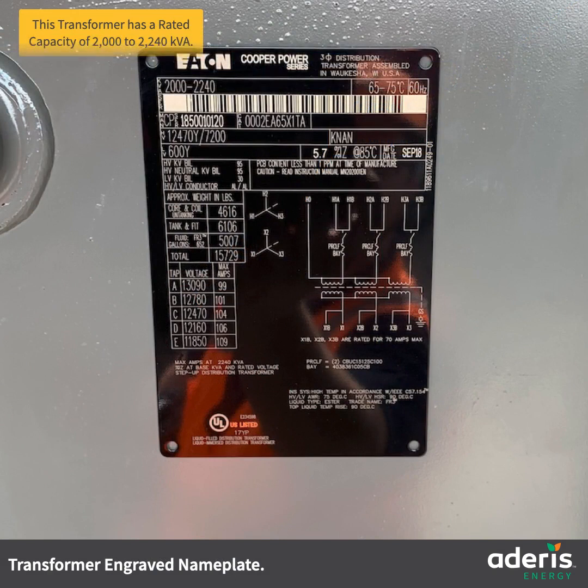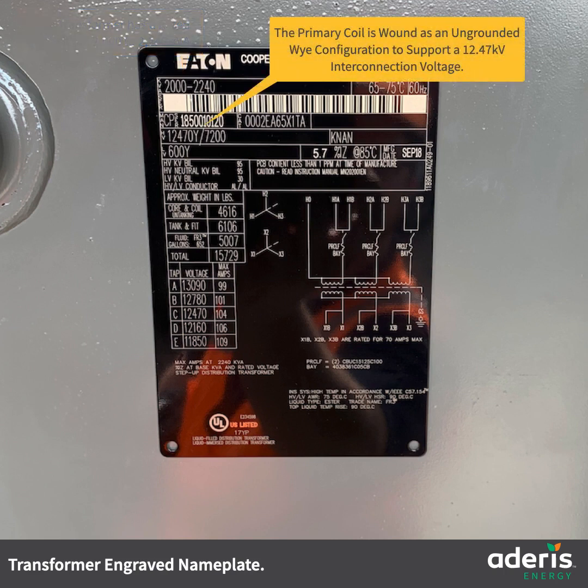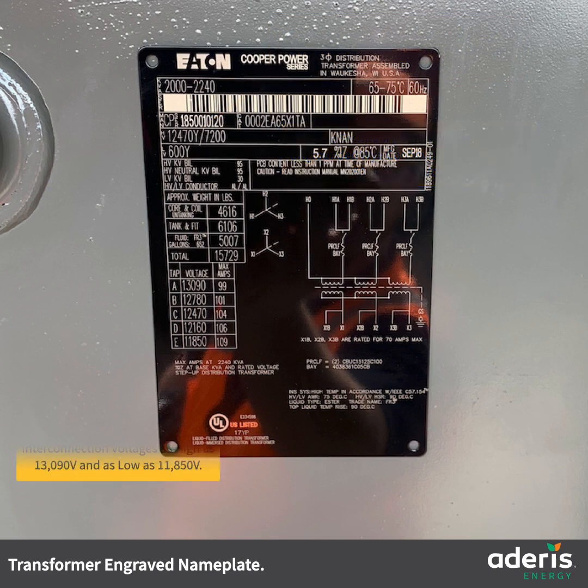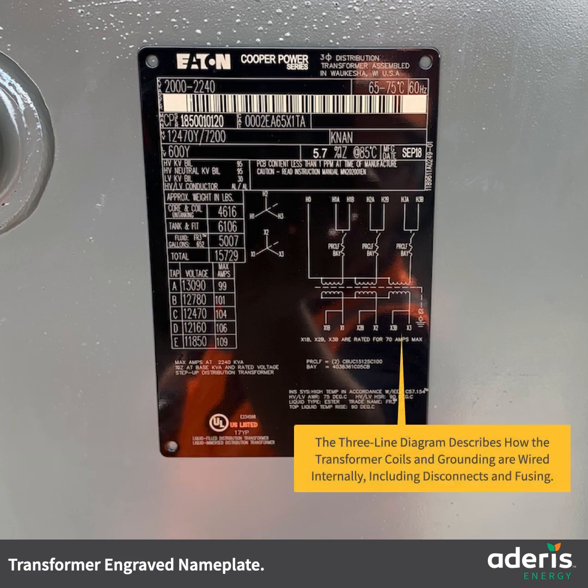This transformer has a rated capacity of 2000 to 2240 kVA. The primary coil is wound as an ungrounded Y configuration to support a 12.47 kV interconnection voltage, while the secondary coil is wound as an ungrounded Y configuration that supports a 600-volt system voltage. Available taps can accommodate interconnection voltages as high as 13,090 volts and as low as 11,850 volts. The three-line diagram describes how the transformer coils and grounding are wired internally, including disconnects and fusing.